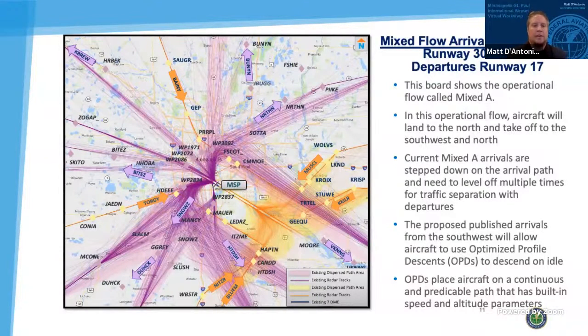Yep. So the darker purple just south on runway 17 is showing historical data from spring of this year. And during that procedure, the tower will basically give fly the runway heading on departure, and then after that, eventually give a turn towards their destination. And so it might be heavily concentrated from that because the airplane wasn't in a good spot to turn, or they weren't ready to turn on course with other traffic in the area for safety.